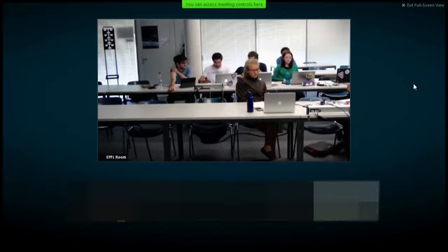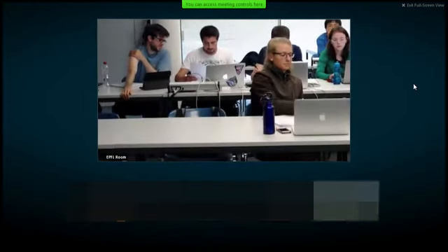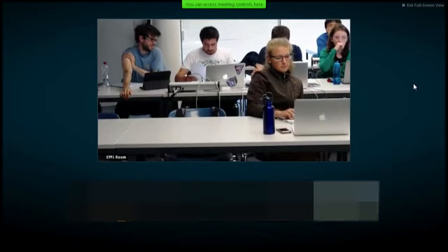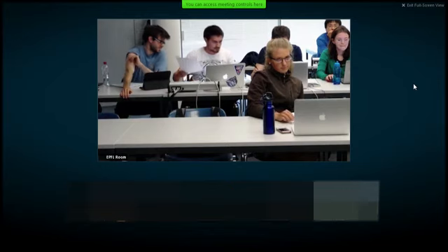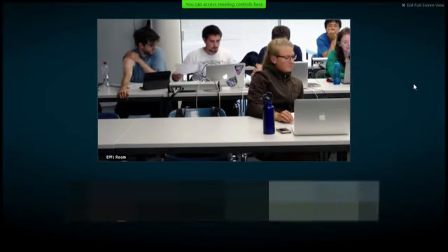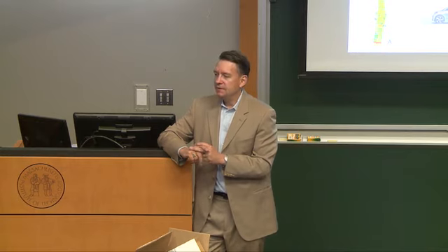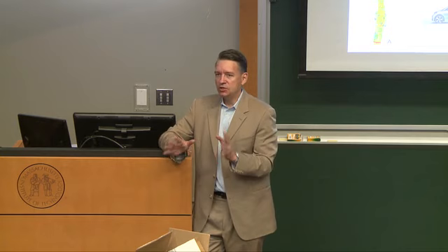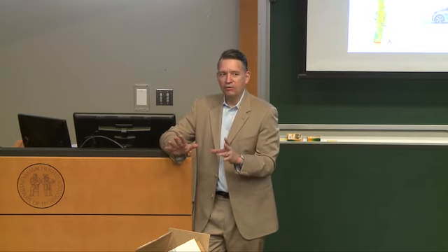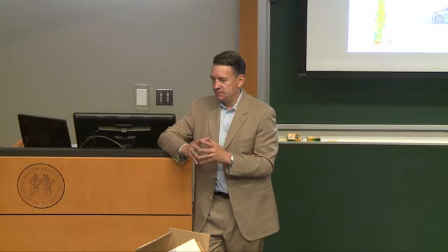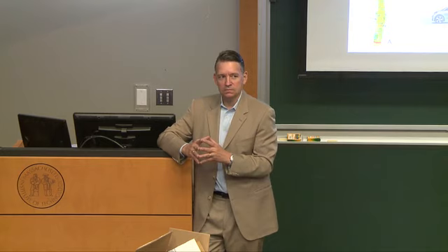Yeah. As a third one, the car shall carry 4 to 5 passengers of average build. And to finish with, the car should be fully recharged in less than a given amount of time. Okay, so recharging. The third requirement is interesting. You said of average build, right? That's the word you used. Yes. Now, that's great. That's a human factors requirement. Now, of average build is a little fuzzy, right? How would you make that more verifiable?